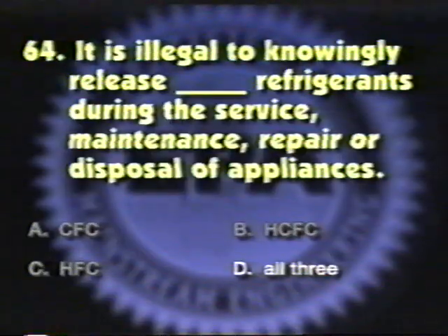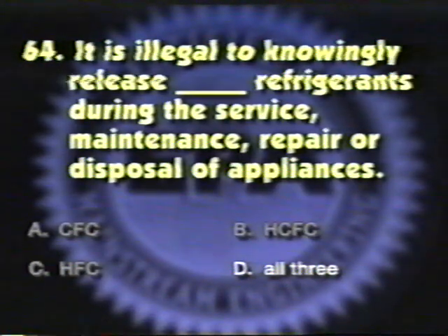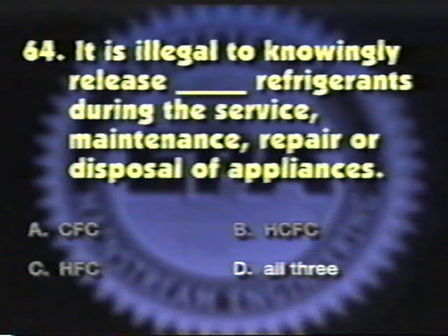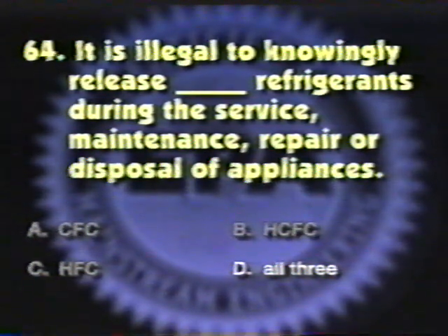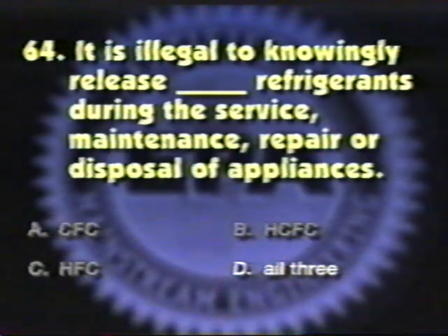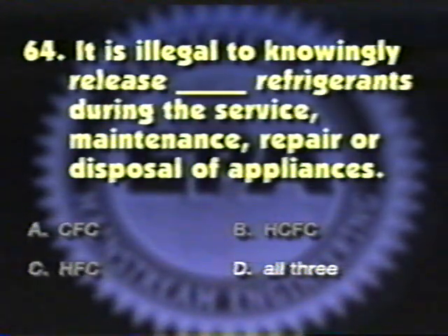The answer is D. CFCs, HCFCs, and HFCs. Since November 15, 1995, HFCs and other refrigerants with a zero ozone depletion potential are also subject to the restriction on venting because they are greenhouse gases, meaning they contribute to the global warming problem and must be recovered.